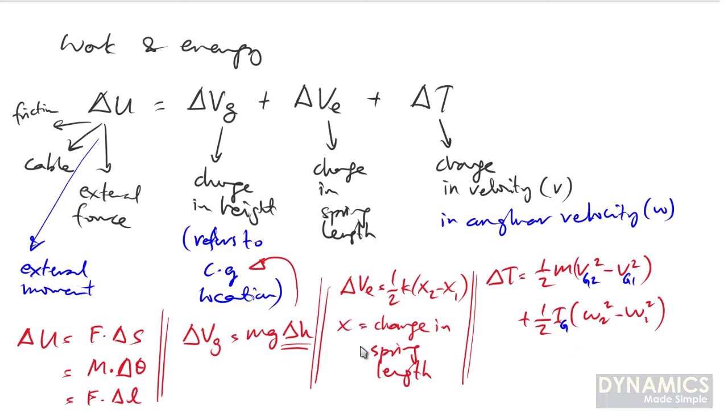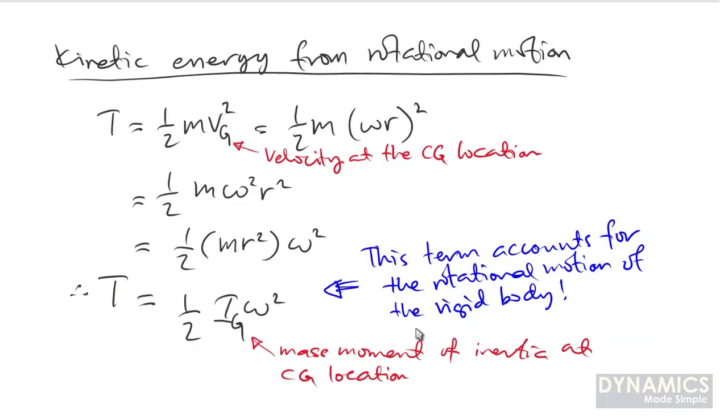Once we have known all of this, we can straight away use the equation inside our problem. What happens if you forgot about this? We can use our kinetic energy terms there. We know that T is equal to half mv squared, and if we replace the velocity with omega r inside this equation, we will have half m (omega r) squared. Since mass is acting at the CG, the velocity must be the velocity at the CG as well.